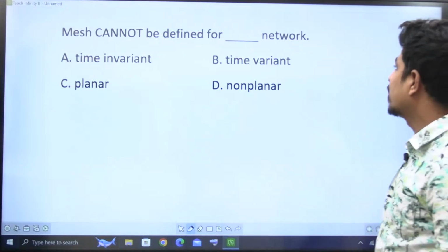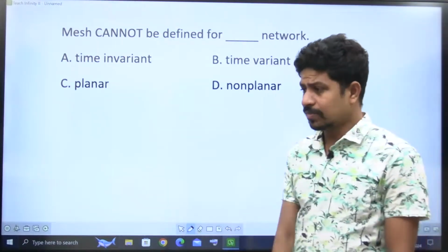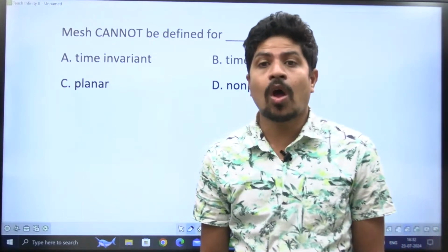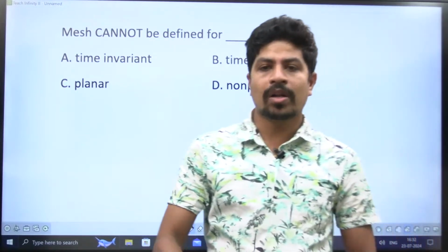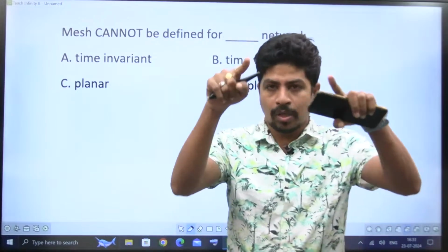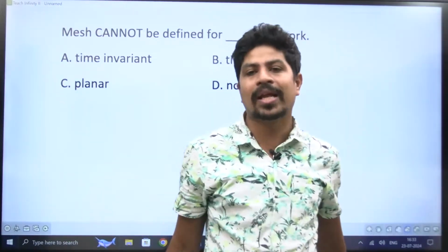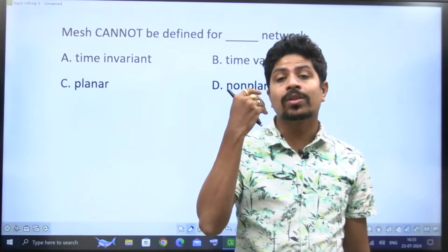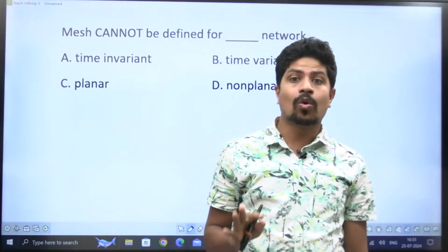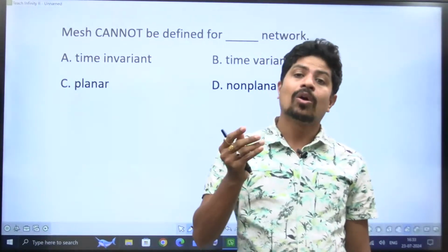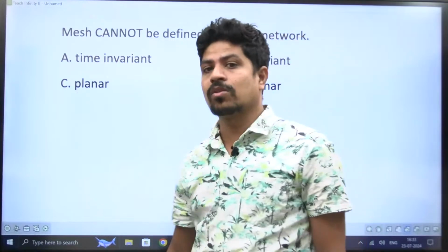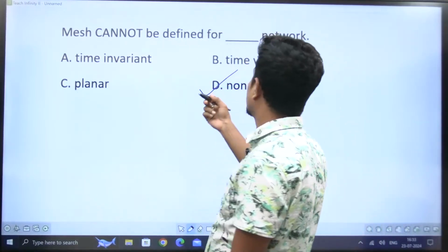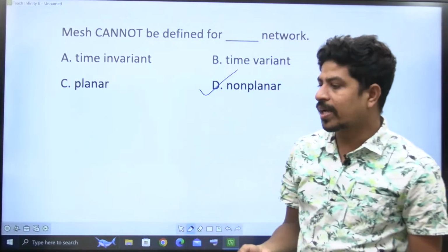Mesh cannot be defined for the network. Yes, I told you this one also in our classes. If it is a non-planar circuit, that means you are not in a position to draw that circuit on a 2D plane, that is called non-planar. Then for that, mesh is not defined, and you can't go with the mesh analysis, but you can go with the nodal analysis. Node is defined. With nodal analysis you can get the correct answer. So for non-planar circuits, mesh is not defined.